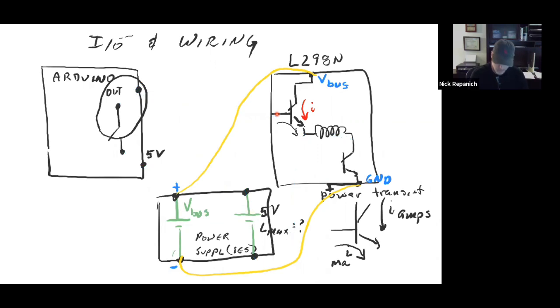I'm backing up there. Let's try again. Maybe I need to go in a different way. Maybe this is a 5 volts out instead of a 5 volts in, which is a problem. So that's where you start needing to label things, look things up, label the pins, draw wires between them, and then find your flashlight.